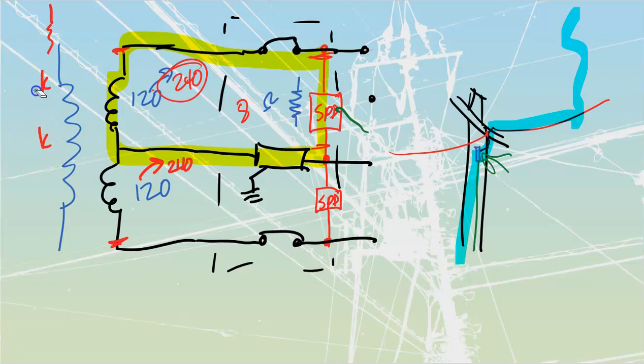We'll sometimes also have them connected across the primary windings of our transformers. If this was a hydro transformer over here, they can sometimes actually have these things built in so that the thyrite resistor is just going right across this. So that if there would be a voltage spike, this is going to go into conduction, which drops the value of voltage, which means that I'm not going to transform that value of voltage through to the other side.